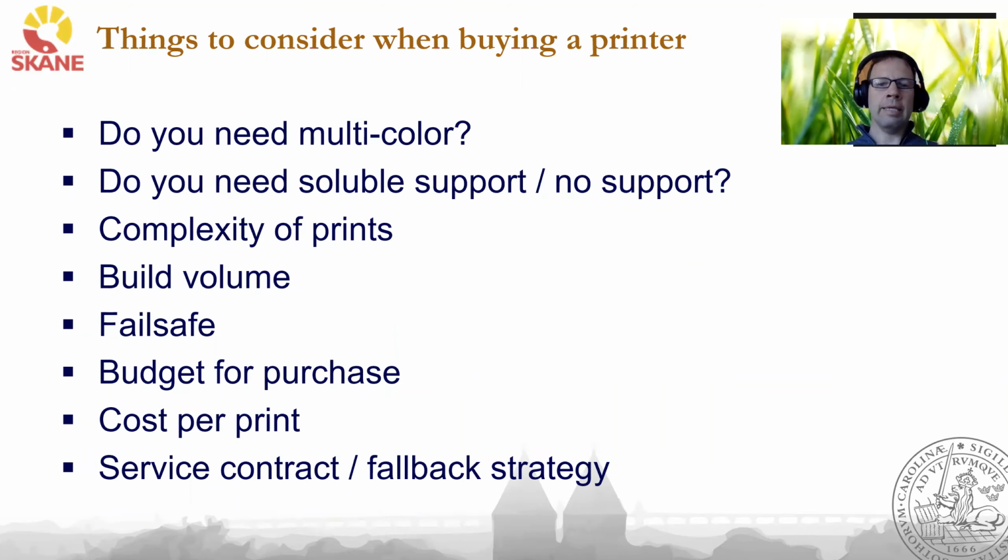So, things to consider when buying a printer. Do you need multicolor? Do you need soluble support, or no support to be able to print without any support? What's the complexity of your prints? What's the build volume that you need? So how big is your biggest print going to be? How fail-safe do you need it? Of course, what's your budget for purchasing? But also what's the cost per print that you expect and are ready to pay?